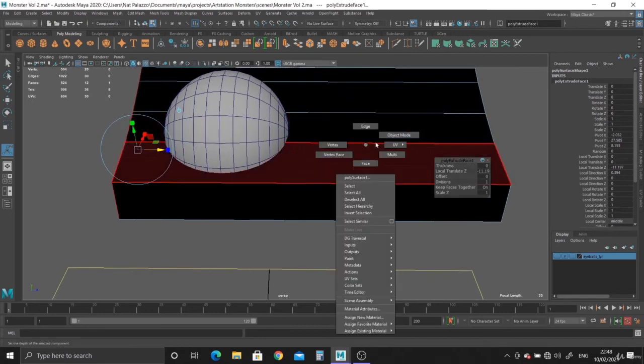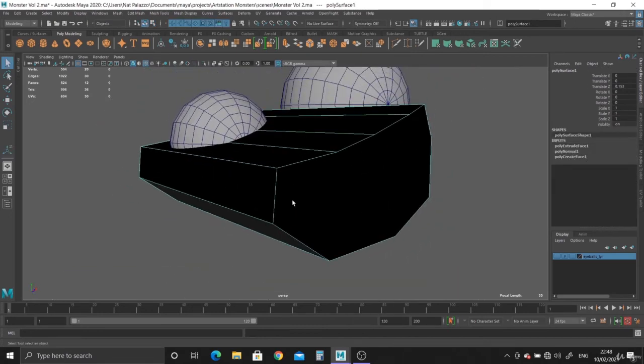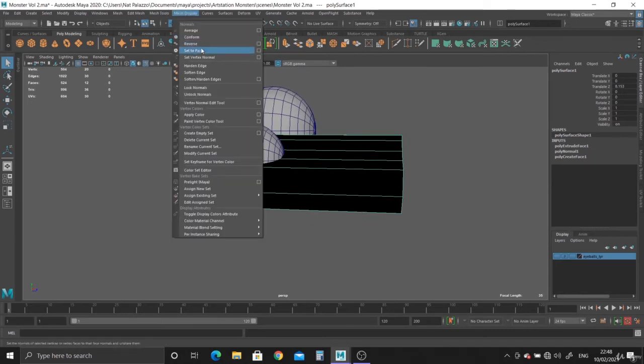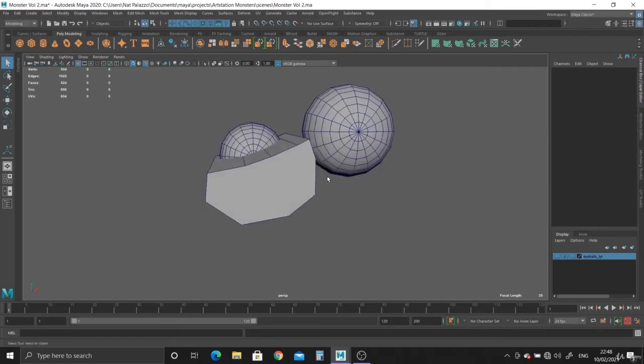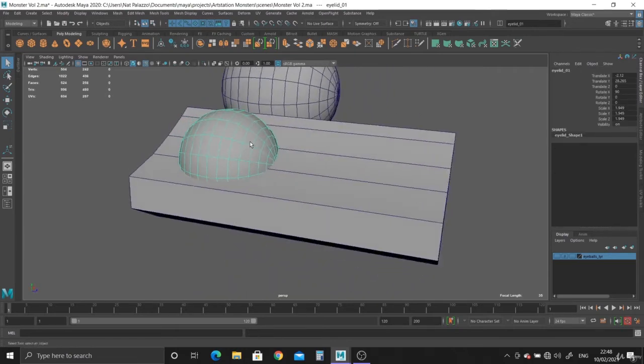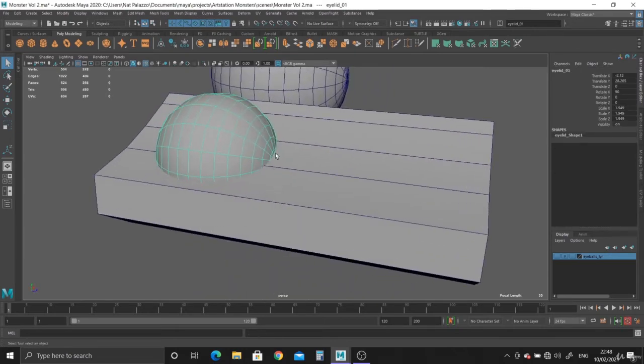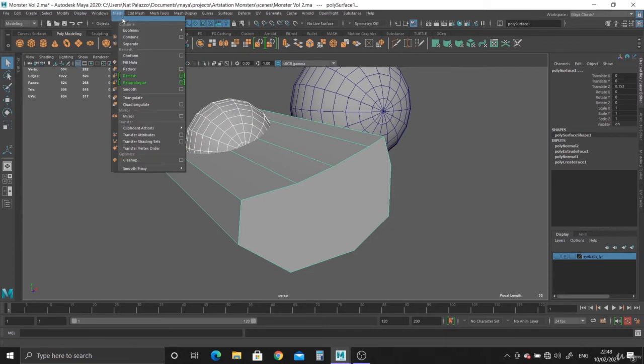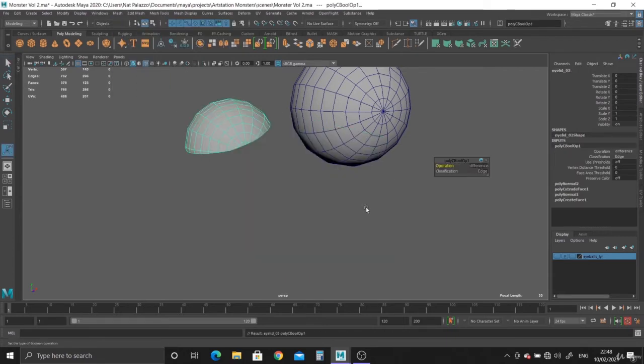You can hit extrude now and just push it back and make sure you go beyond the geometry here. So we've created our Boolean object, and as you can see, it's inside out again because we pushed it back in negative space. So again, all you need to do is go to mesh display and boom, reverse, and there you have it. So always select the geometry first that is going to receive the booleans. Hold down shift, then select the boolean geometry, just go to mesh, boolean, difference, boom, there you go.